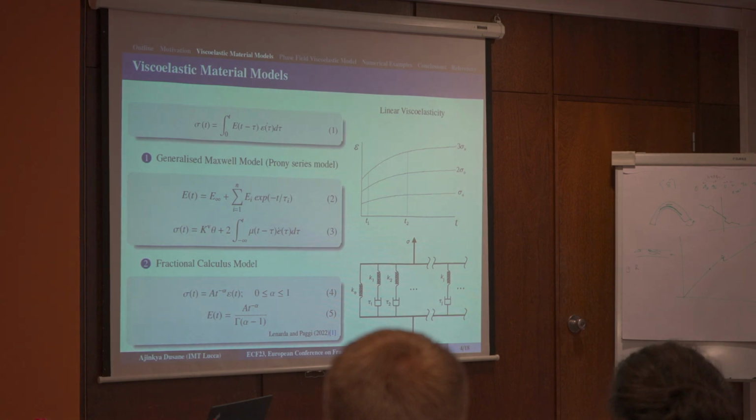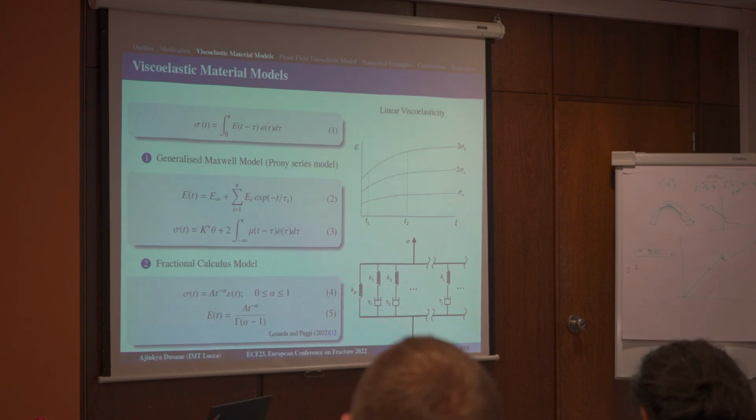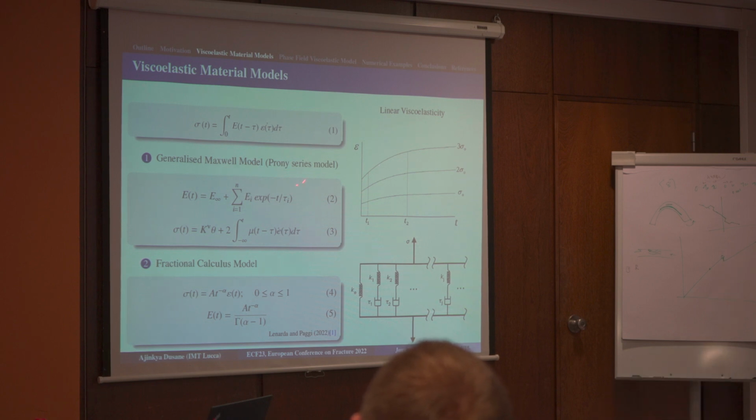The study of viscoelastic materials is called rheology. In rheology, a variety of models are described based on combinations of springs and dampers. The spring takes care of the elastic part, and the damper takes care of the rate-dependent strain part. The basic model is sigma(t) proportional to the rate of strain, the damping effect. But in our formulation we are restricted to linear viscoelasticity, where the strain is proportional to the stress.